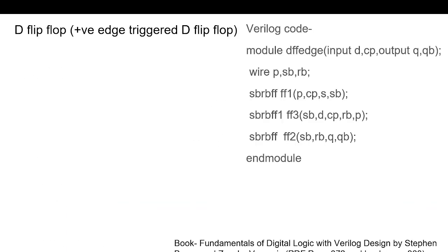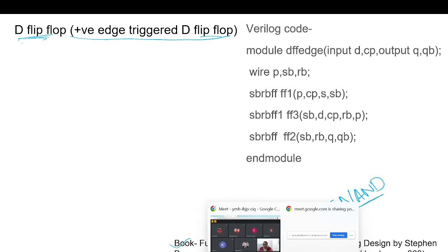Yes. Next we will design the flip flop. So the D flip flop, okay. Either we can have a master slave combination for the D flip flop, or a positive level triggered D flip flop, some optimized version where we just need 6 NAND gates, which is given in this book, and the circuit is